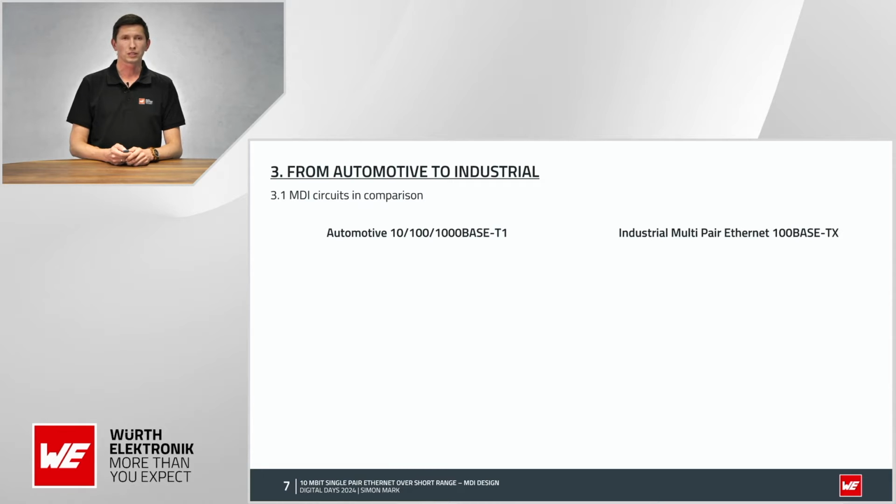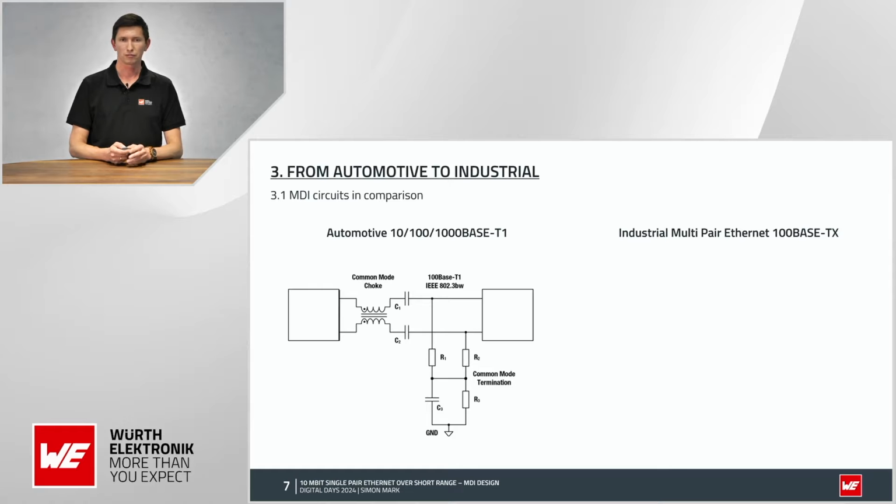Now we go to the MDI, the media dependent interface. For automotive, for 10BASE, 100BASE and 1000BASE-T1, you have the same recommended circuit. Starting from the left side, from the PHY, you have the common mode choke, some capacitors and a common mode termination, and the automotive connector.